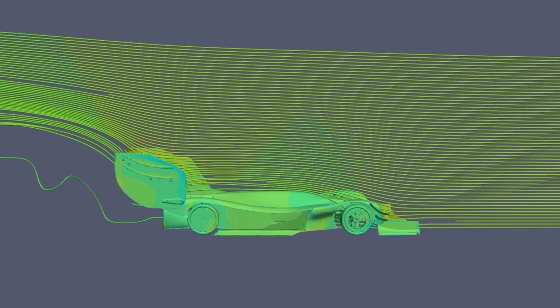Lastly, the order of design and optimization of your aero devices is very important. So I initially designed and roughly optimized the largest aero device, which is the underfloor. Once I had that worked out, I worked from the front to the rear of the car. This is important because it's very easy to design an aero device at the front of the car that makes more downforce at the front, but subsequently ruins the aero performance downstream.